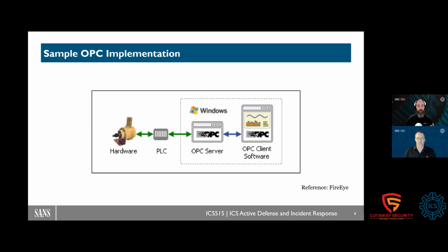We're looking for a read-only capability, but of course, with OPC Classic you're reliant on the application-dependent configuration to prevent those writes. So it can be a bit tricky, but quite often it's used as read-only. It's got that capability of write. And digging in deeper, OPC UA, which again has been around for a long time but we don't see a lot of use, has a bit more capabilities around that read-write side.